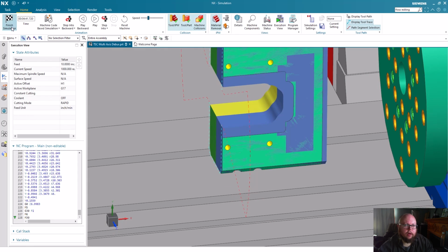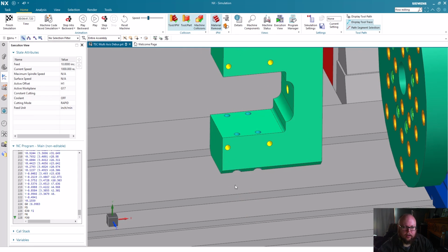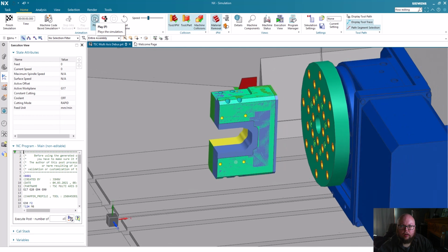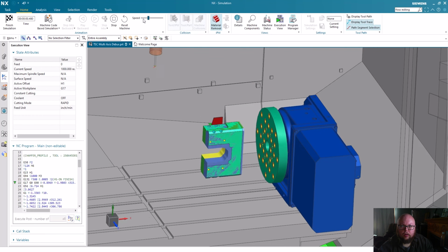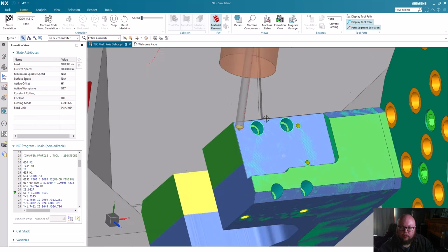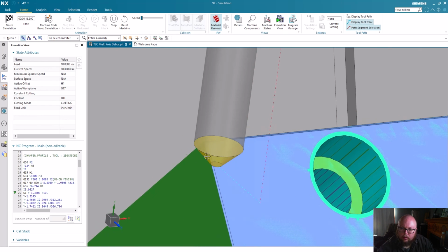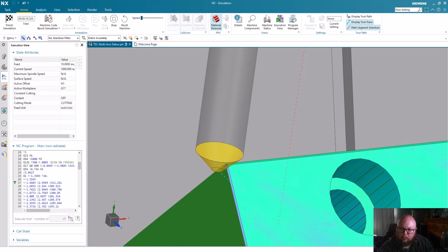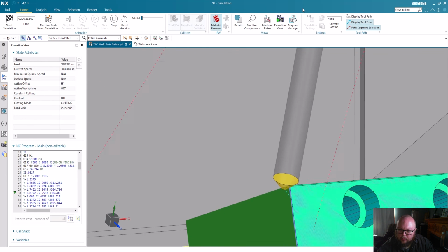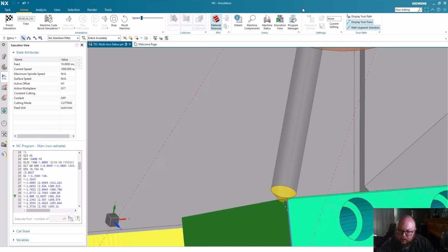Let's bring this back around. And maybe I'll reset this and we'll just take one final look at it. We slow it down and come in. We're chamfering this first corner, making some A motions right away. So you can see it's interpreting all those individual linear segments.